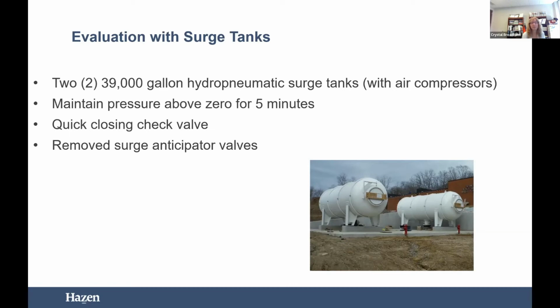This particular client had contract pressure requirements with several of their larger users. So we sized these surge tanks to make sure that we were above 0 pressure for at least 5 minutes, with the idea that they can get the pumps restarted within 5 minutes.